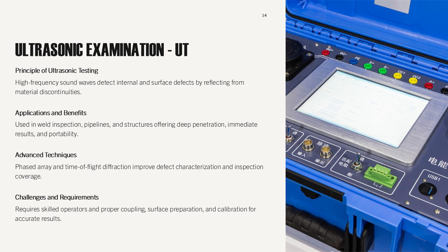Advanced UT methods such as phased array and time-of-flight diffraction enhance defect characterization and coverage. UT is widely used in weld inspection, pipeline integrity assessment, and structural evaluations. Proper coupling, surface preparation, and equipment calibration are essential for reliable results.